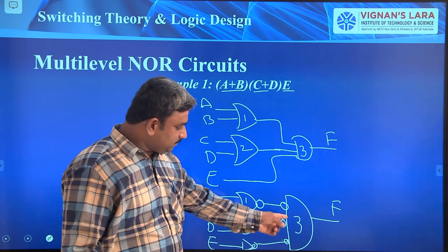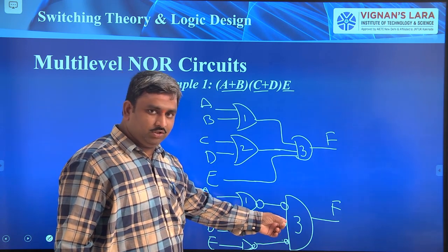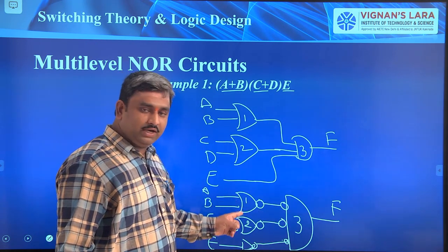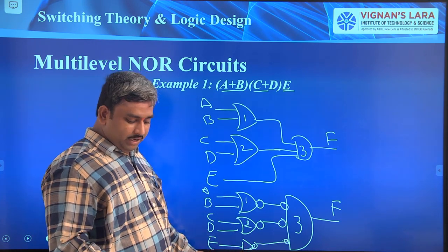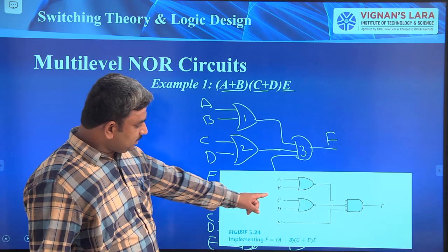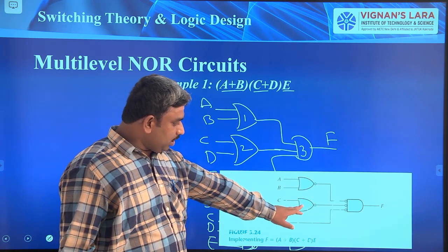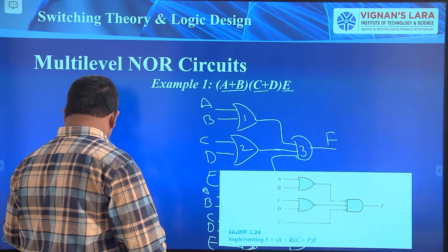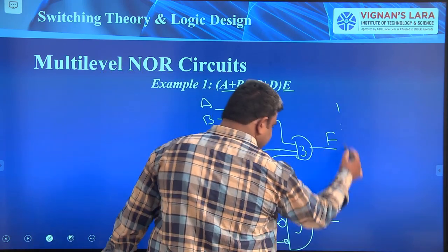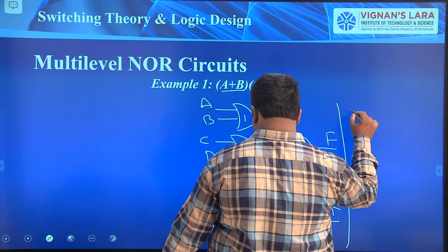Okay. So this bubbled AND we can replace with a NOR gate. These NOR gates are directly available. This NOT gate also we can implement by using a NOR gate. Okay. So finally this is the circuit. So 2 NOR gates and a bubbled AND gate are available. Now convert this function. So the final step, coming to the final end step.